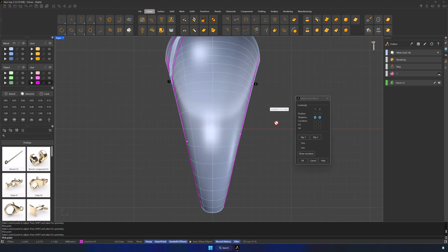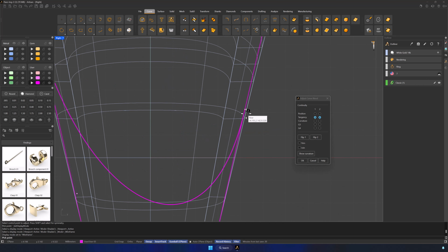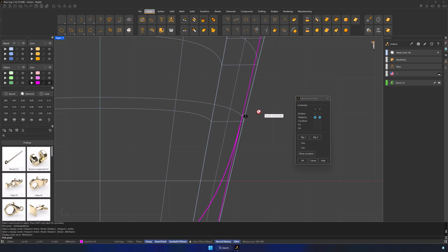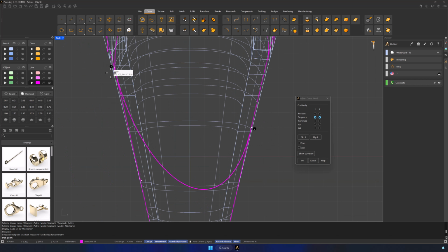To see this better, activate wireframe mode. Adjust the points to a height of 2 units above the axis. Use the grid as a reference. To move them, click on a point and position it. Then click again to set it in place. Take your time to adjust the curves. It may be challenging at first.